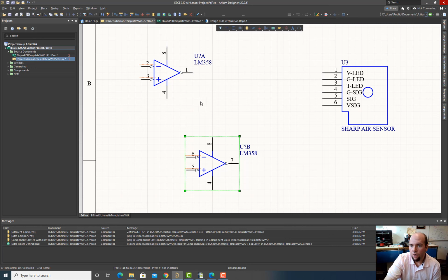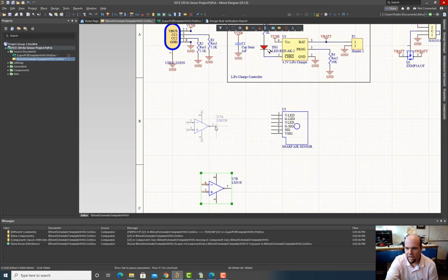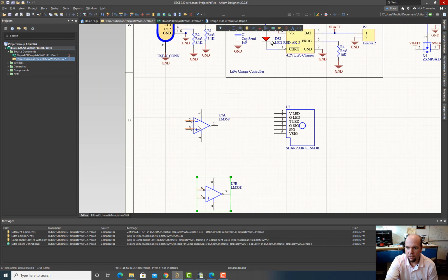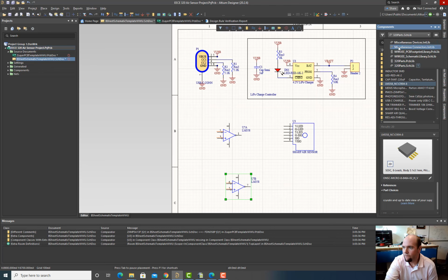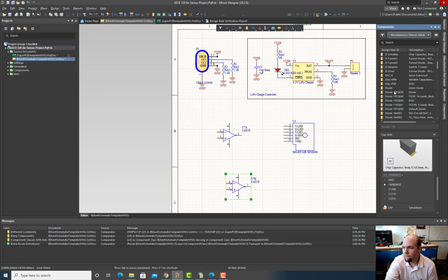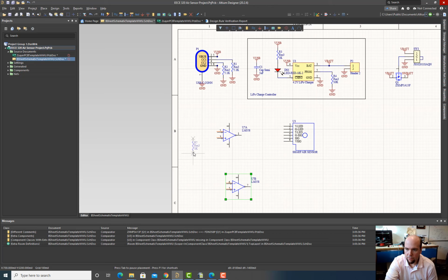So, okay, I dropped those 2 op amps, again corresponding to one physical chip. Now I'm just going to build the circuit for the Astable multivibrator here. Res 3, 0603, place it. So I gotta go back to my design.